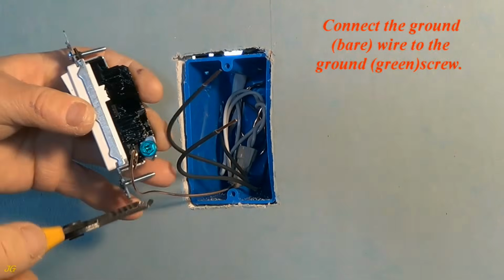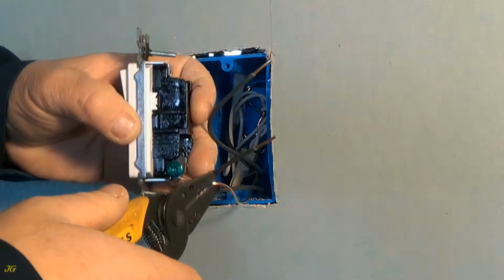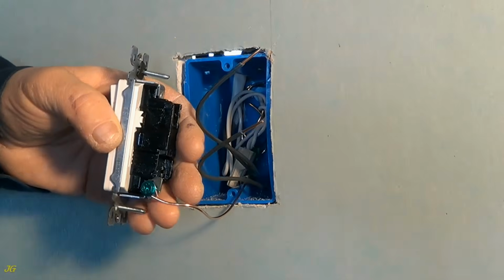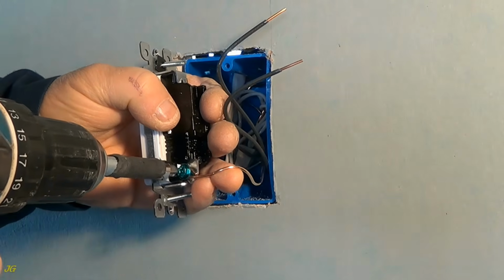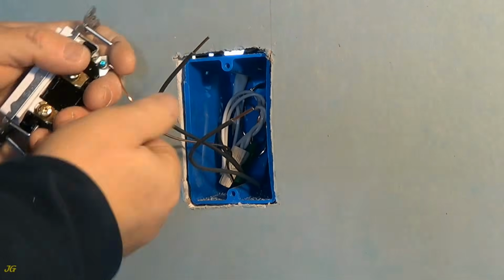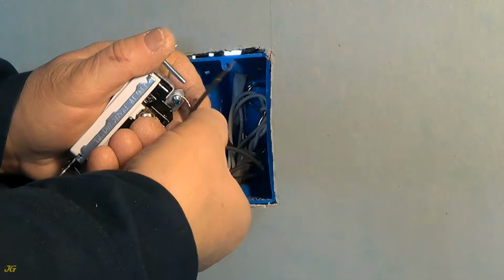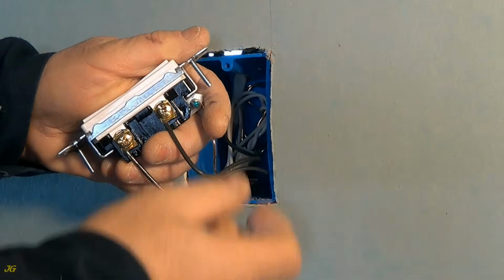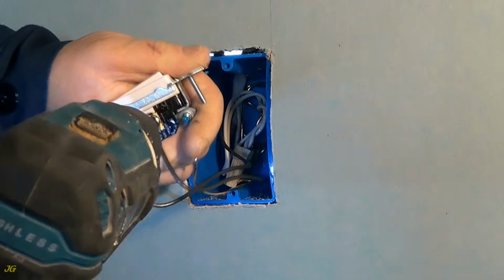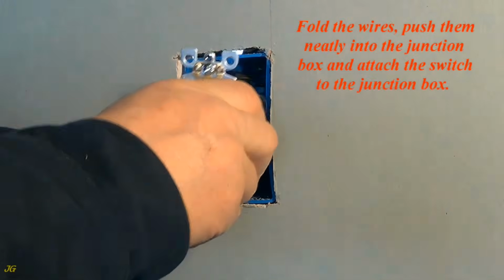Connect the ground, bare, wire to the ground, green, screw. Connect the two hot, black, wires to either of the two hot, gold, screws. Fold the wires.